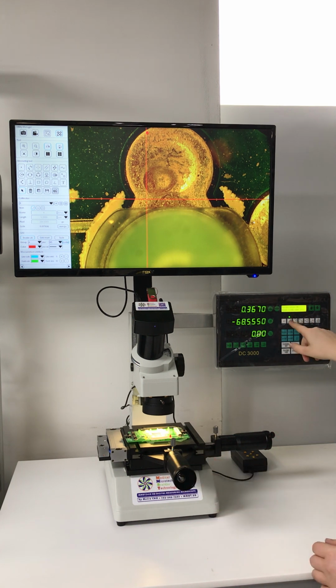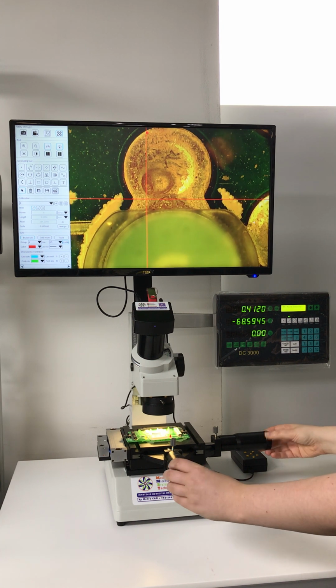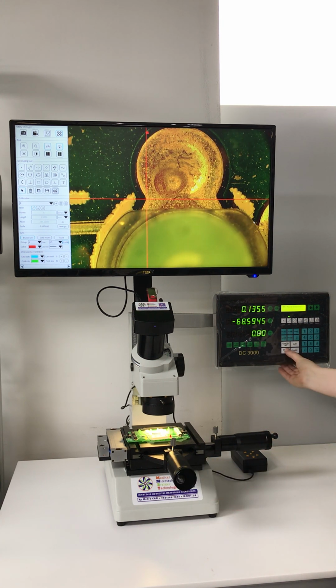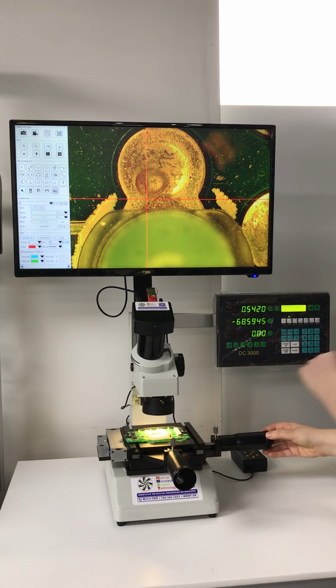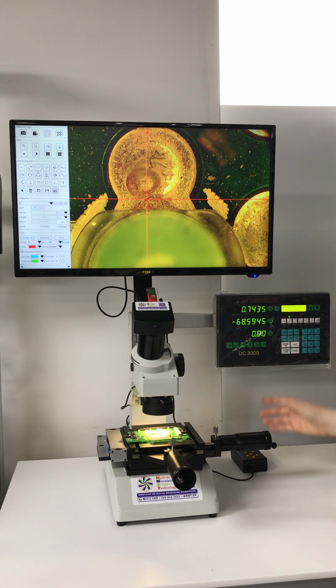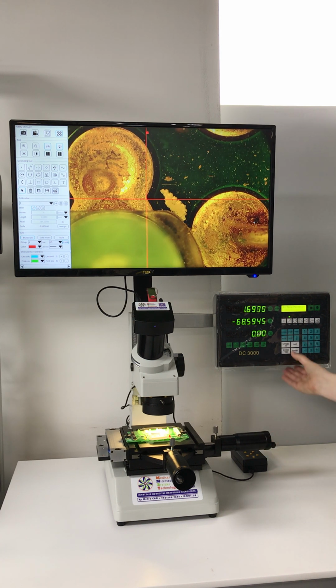So again, I'll press line. Let's do 5 points. I will line up my part, press enter, and do 4 more points. And as you can see in the readout, it'll keep track of which points I'm on and tell me how many I have left. Press enter. And as you can see, press more for more information. It'll tell you the angle or any more. When done, press finish. You can go to your next point.